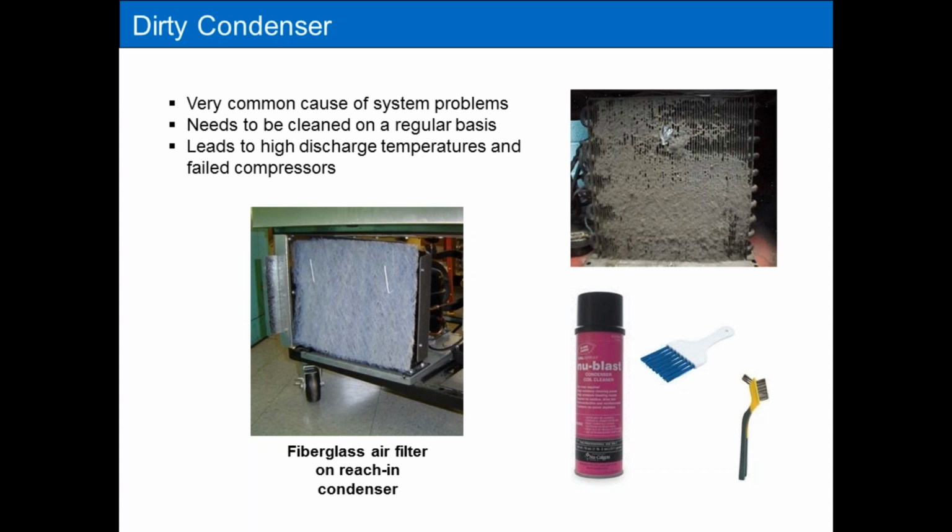So what I found is best is to brush them down. Brush in line with the fins. Take a decent brush. It doesn't have to be a real hard brush. It could be a pretty firm but soft brush, if you know what I mean, kind of like a strong nylon brush, and wipe it down. Brush it with the fins and get rid of the dirt that way, rather than blowing them out.